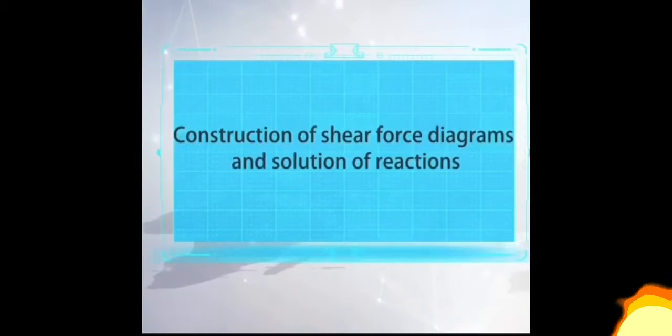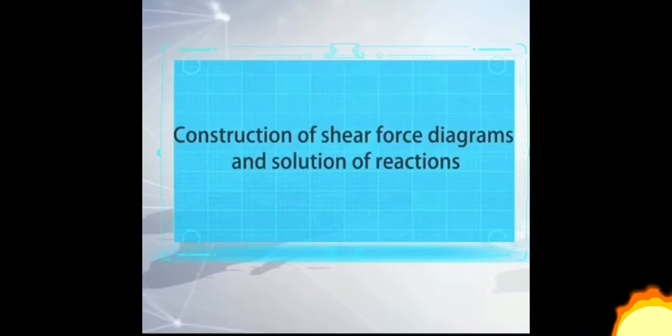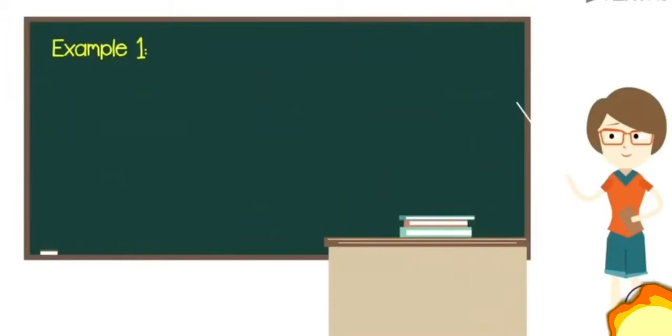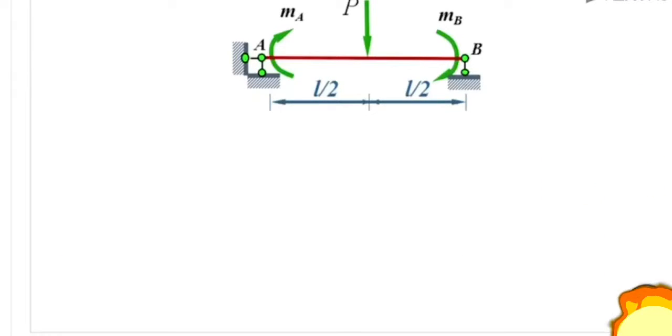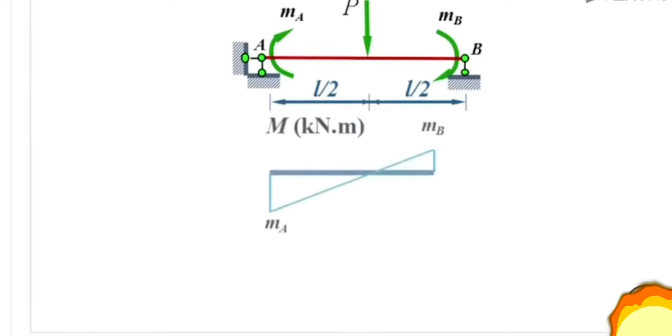Learn how to construct shear force diagrams according to bending moment diagrams and solve reactions according to shear force diagrams. Last time, we discussed how to construct a bending moment diagram according to the superposition principle. Only under the action of two end couples MA and MB, we could construct a bending moment diagram.